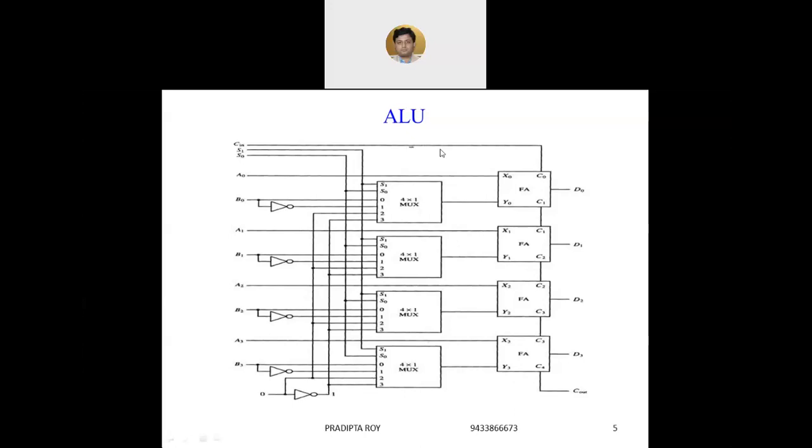If we try to represent value 1 with 4-bit numbers, it should be 0001. Now if we find the two's complement of this 0001, our output will be 1111. So that is propagated to the Y input of the arithmetic circuit, and the A input is directly connected to the X input. So basically we are trying to perform A plus 2's complement of 1.